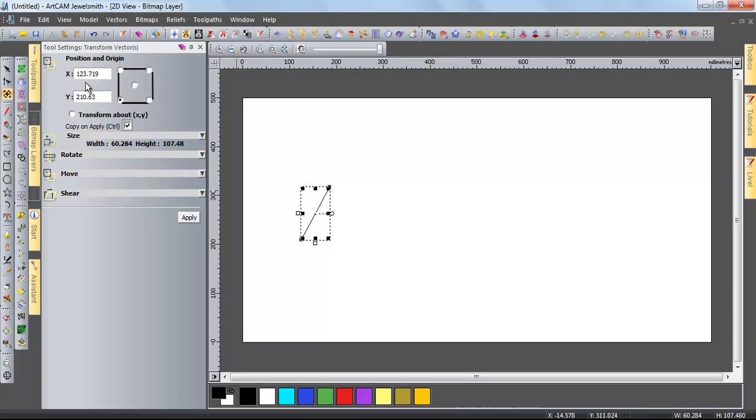Here we measured 123 points as 719. I want this to be 123, 200. If you want it to be 200, it will position it as 200, but it will position it by copying it. As you can see, it's 200, so it's brought to 200 here, x, and brought by copying. While this is active, as I said in the name, it always copies the transactions we have made.